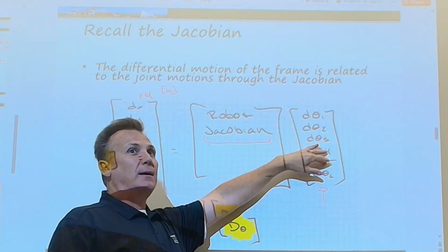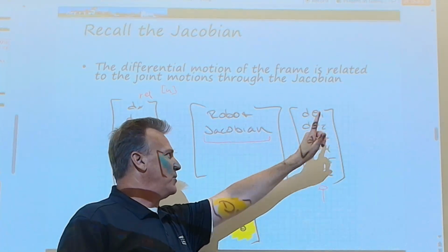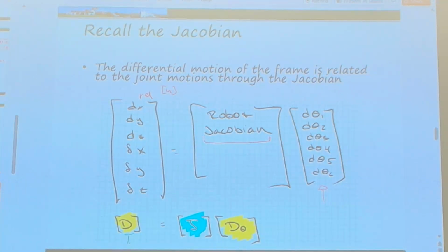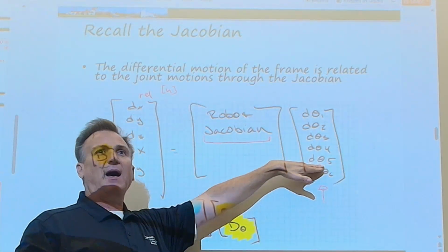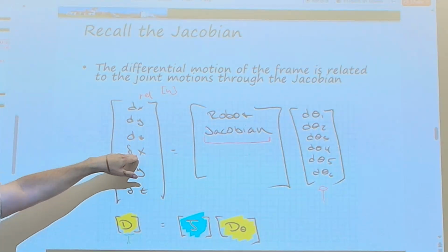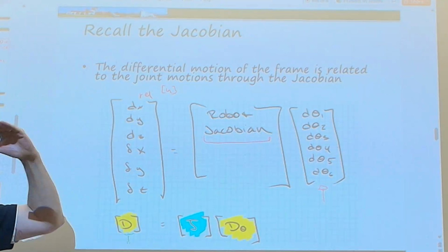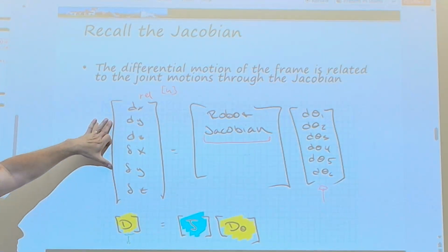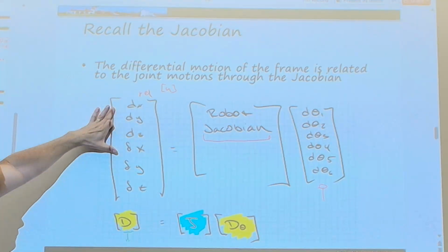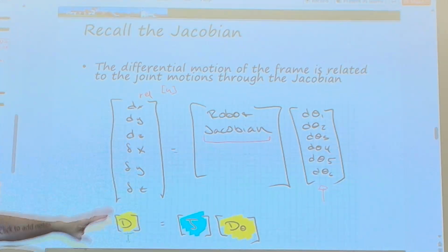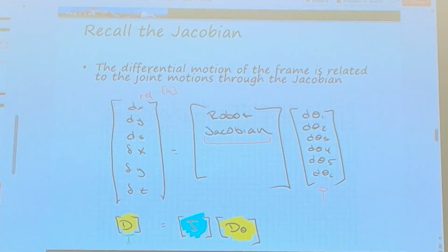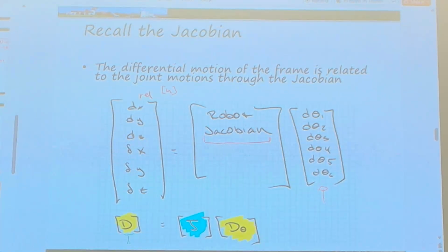It's not a 1-to-1. And so if I'm controlling this to theta 1 and that to theta 2 and that theta, and all of them are adjusting the velocities ever so slightly to get absolute thetas at the sacrifice of changing my theta dots, that means this will not be the same velocities that I would have, because they're all going up and down, correct? But that net result may put me at some offset in the displacement. If I integrate these deltas, these differential positions, these small changes, then where I end up in that space may not be where I wanted to, because yes, all of my angles are where they need to be, but I may no longer be where I'm supposed to be.